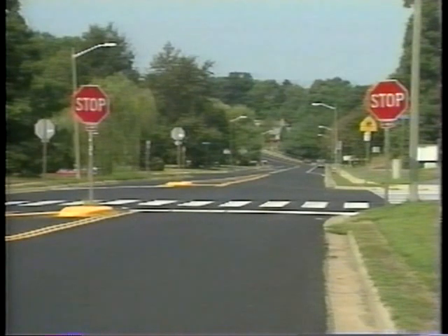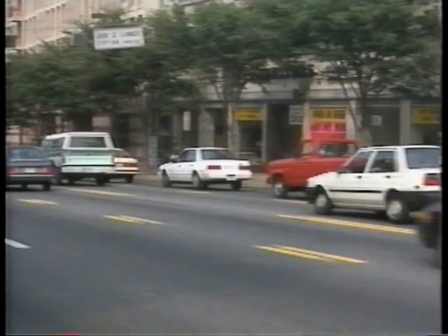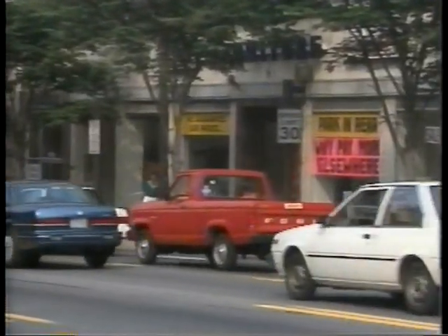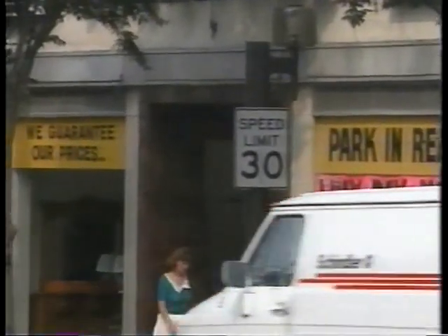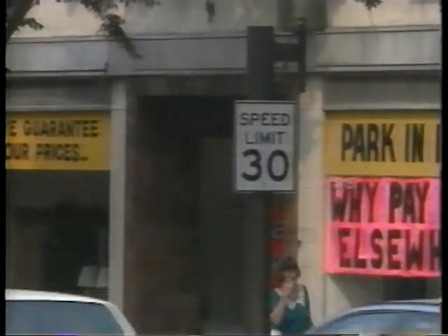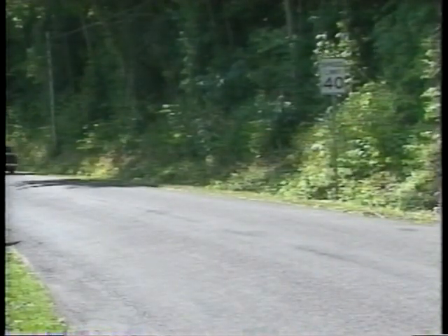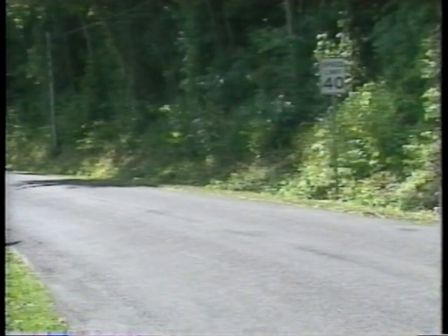Wider streets, channelized intersections, or one-way roads should have a second sign on the left as well. A critical non-intersection sign is the speed limit sign. These signs are put up under two conditions. First, whenever the speed limit changes. Second, additional signs should be put up if drivers need to be reminded of the speed limit.